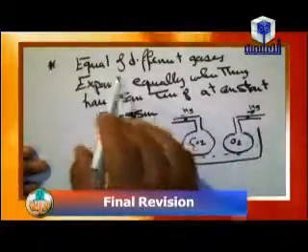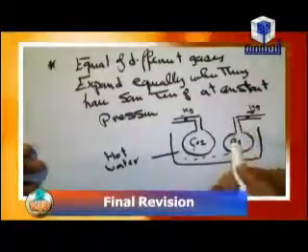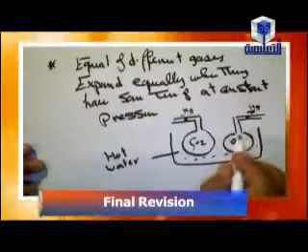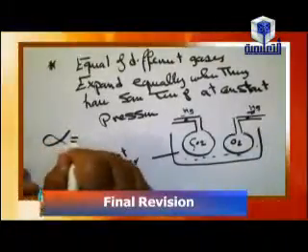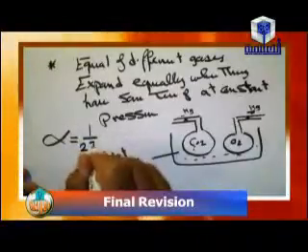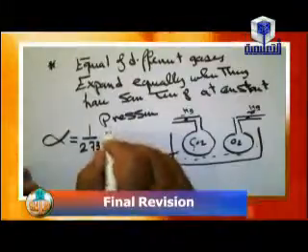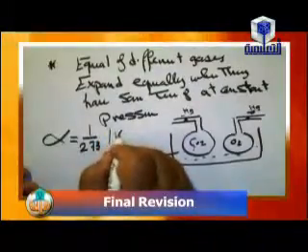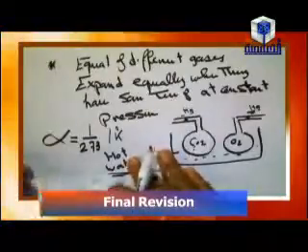That means equal volumes of different gases expand equally when they have the same rise in temperature at constant pressure. That means alpha, the coefficient of volume expansion for all gases, is equal to 1/273 per Kelvin or per Celsius. This is called the coefficient of volume expansion.